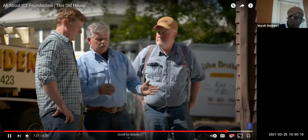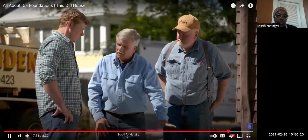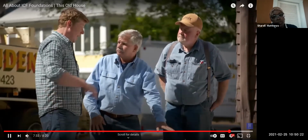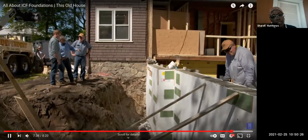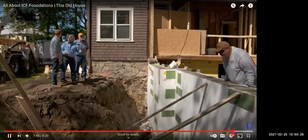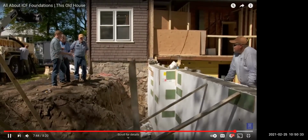When you build a concrete foundation, you pour it. The building code only requires that you insulate it from the grade down, not above it. That's where you need the insulation. Exactly. So now this is insulated not only on the outside, but the inside. So it's insulated to an R25 and it's airtight, all the way up.